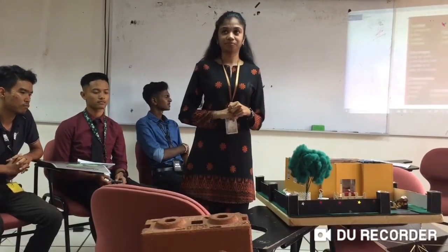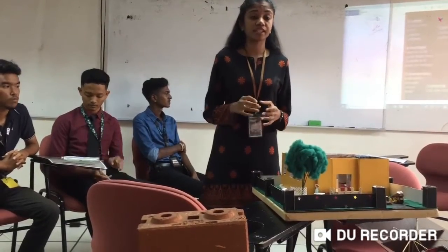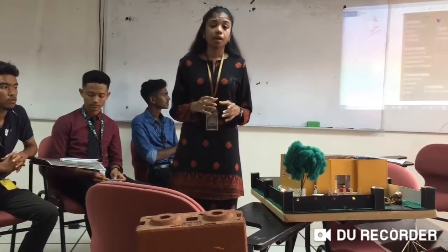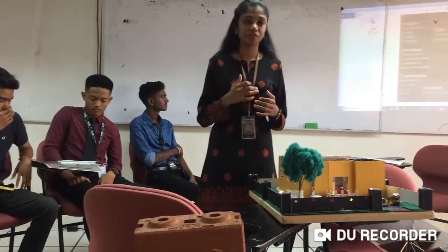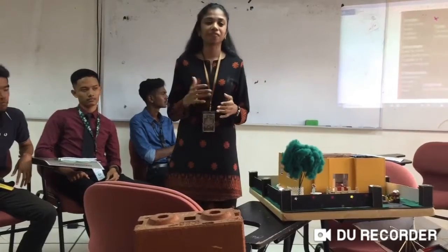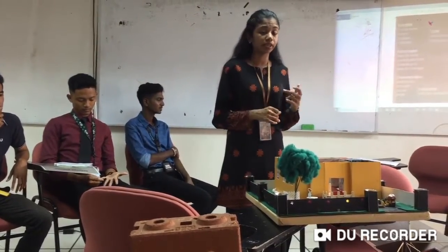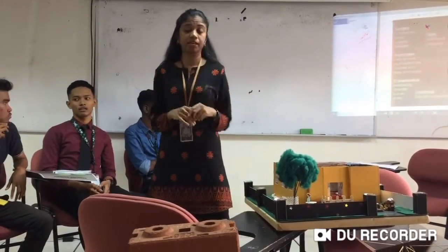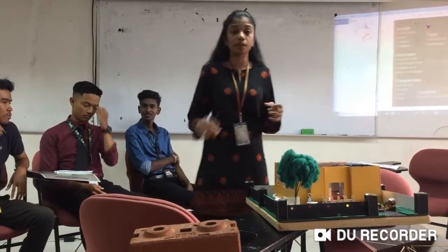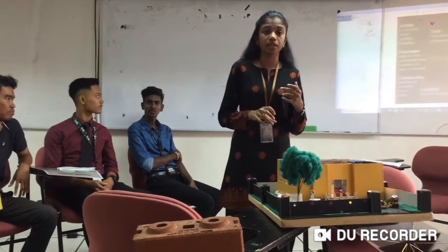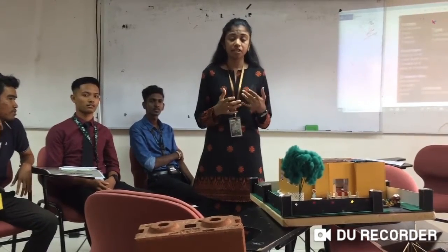The appearance of the timber depends upon the arrangement of cells in its structure. If they are arranged in a uniform manner, a uniform appearance of the timber will be obtained after cutting. We can usually find some fungal defects on the timber, which are blue stain and sapstain. They can damage the appearance of the timber. Blue stain, in an easy way, is some kind of fungi that makes the timber bluish, while sapstain is some kind of fungal attack on timber which makes the timber discolored.